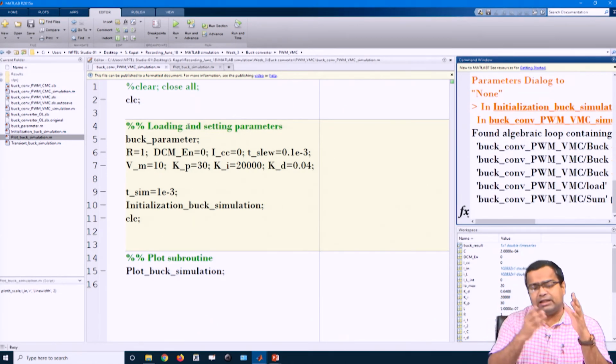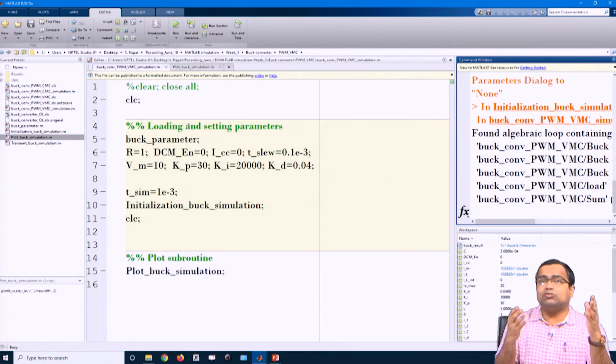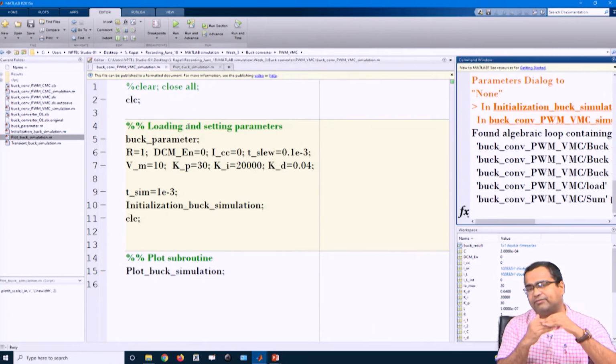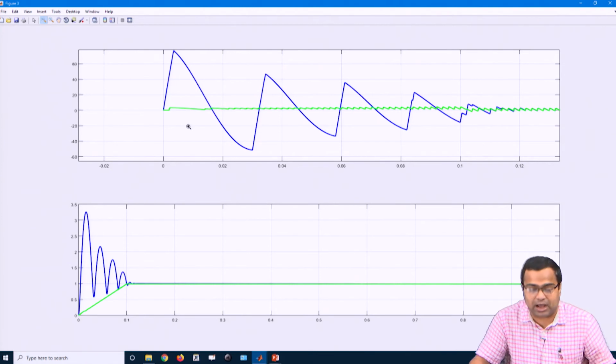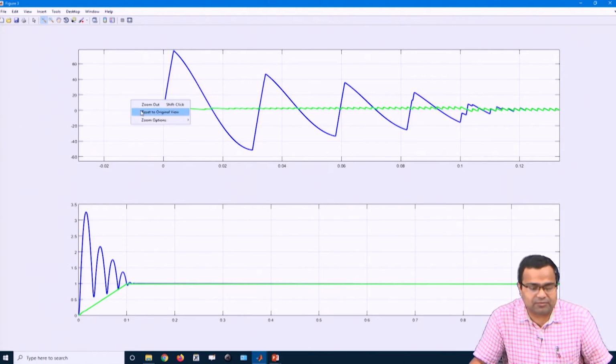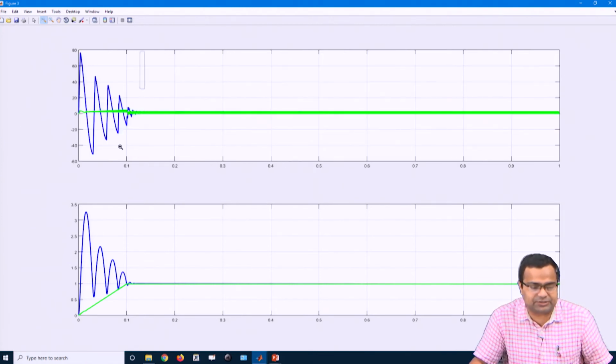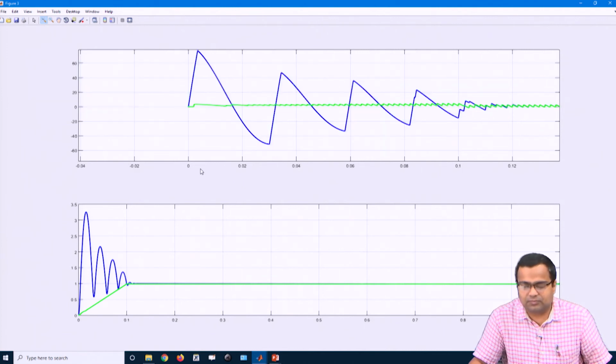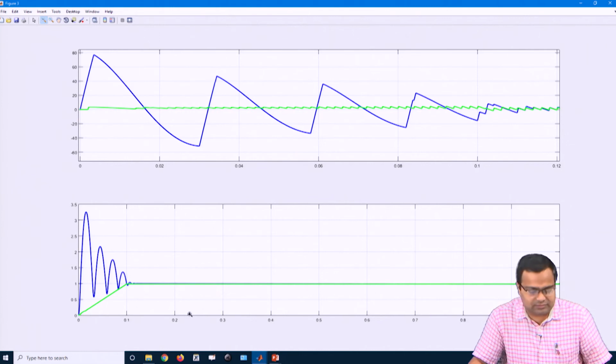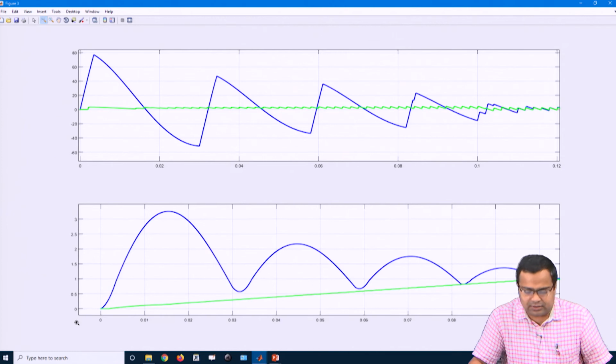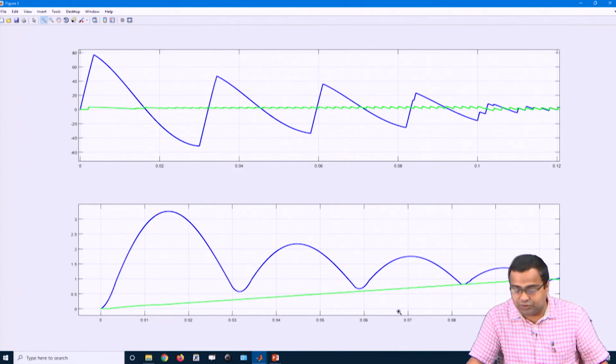If the slew rate is too fast, then it is as good as applying a very fast Vref at the beginning. But now you see we are putting a limit in the Vref, and we want to change the voltage from 0 to 1.